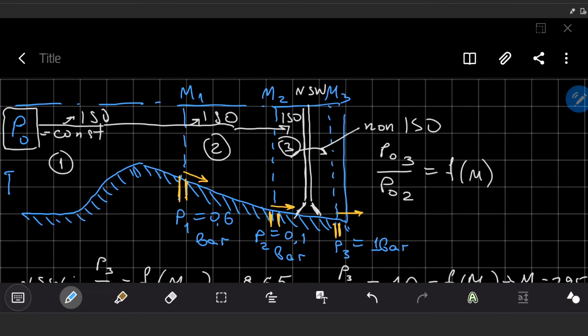For example, we know that T0, it's very easy. Put the thermocouple inside the tank, the flow is not moving, so you measure exactly the stagnation temperature. It will be a bit elevated with respect to the ambient temperature. Okay, let's assume 400 Kelvin.